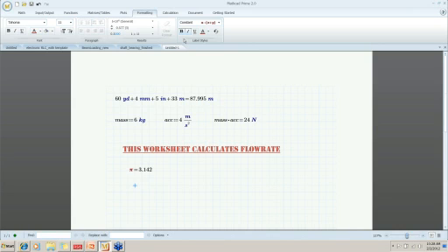Now also on the formatting tab while we're here, we have the ability to format numerical results. So if we go to pi, by default we're displaying 3.142, but if I select that and go up here under result format and select scientific notation, that should convert it to scientific notation.